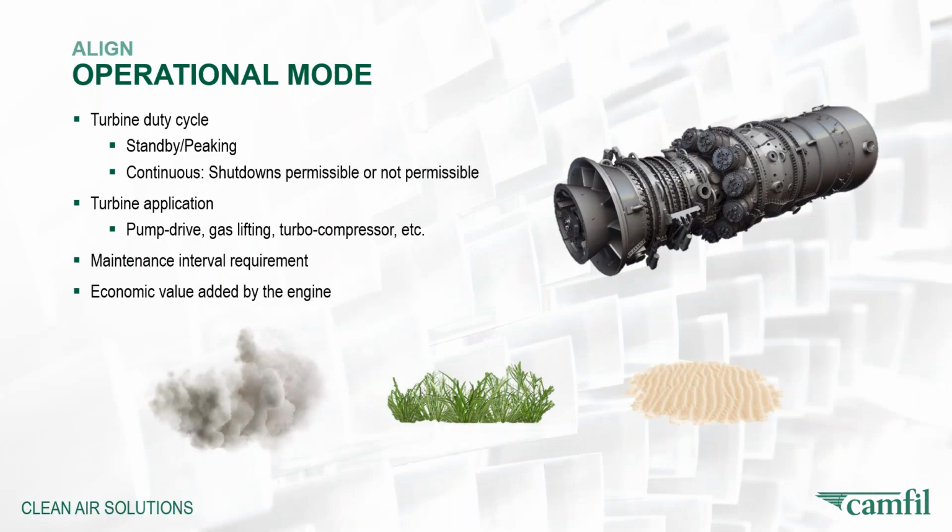So when looking at the selection criteria, it's necessary to consider the application of the gas turbine and functionality requirements. Ask yourself, is that engine running at base, intermediate, or peak? Does the application require minimum shutdowns, such as an LNG terminal, or have a routine maintenance interval which allows for more frequent planned outages? What's the application that the engine's driving? Is it pump, compressors, generator, etc.?